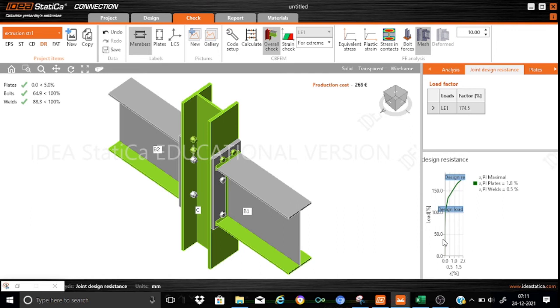As you can see, here is a graph of the load increment versus the strain. Here we see that this factor of 174.5 percentage corresponds to a strain level. That means any one of the components could be taken to a strain level of 2 percentage when we approach a factor of 1.74. So in order to demonstrate, I'll just multiply my original moment of 300 with this 1.74, just for demonstration purposes, and let us see what plastic strain levels get developed in the model.